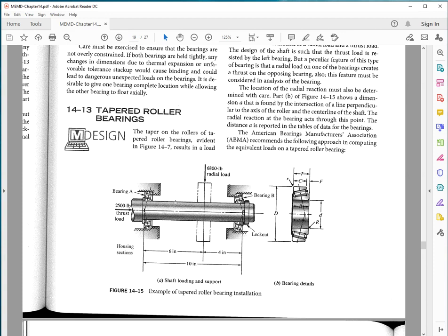And you see them used the way it's said. So they are close to each other, the X arrangement. They have some angular compliance, and on the opposite end you have a 3rd bearing. I've seen that with some automobile transmissions where the shaft was the bevel pinion shaft, the one that meshes with the ring gear on the differential.